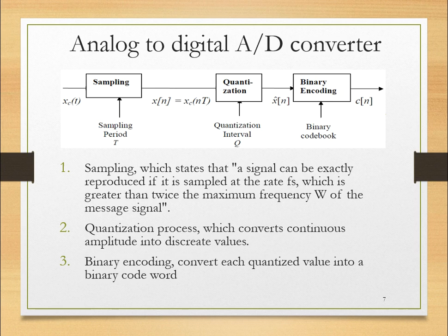Encoding, each level, you can map it to a certain binary sequence. And then you collect all these sequences together, and you say that this sequence represents that analog signal. Now you can deal with this sequence and process it using your digital algorithm, using your computer, using the resources you have, which turns out to be very useful, because we cannot process analog signal.